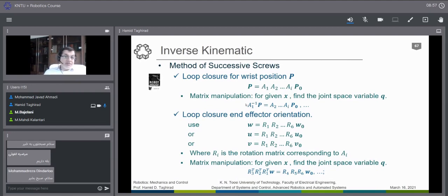You can use ATAN2, you can use a linear equation with a matrix equation for a parameter that can be solved, you can use half tangent, you can use a geometric approach. Any means that you can solve this nonlinear equation should be considered here. This is usually used for the positioning vector and finding the first 3 or 4 joint angles or joint variables.